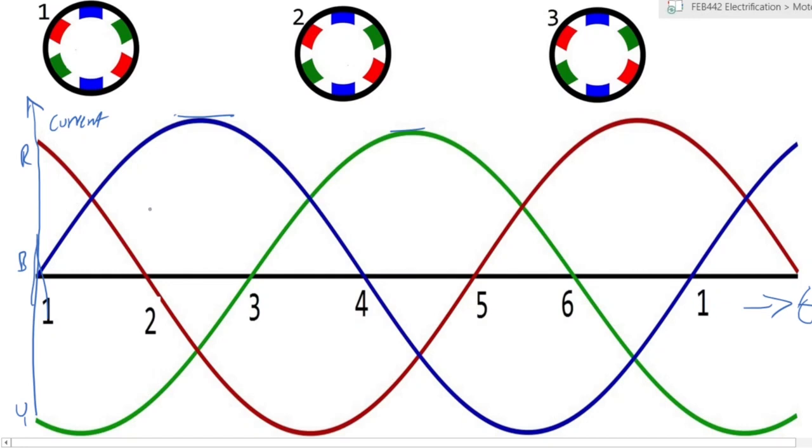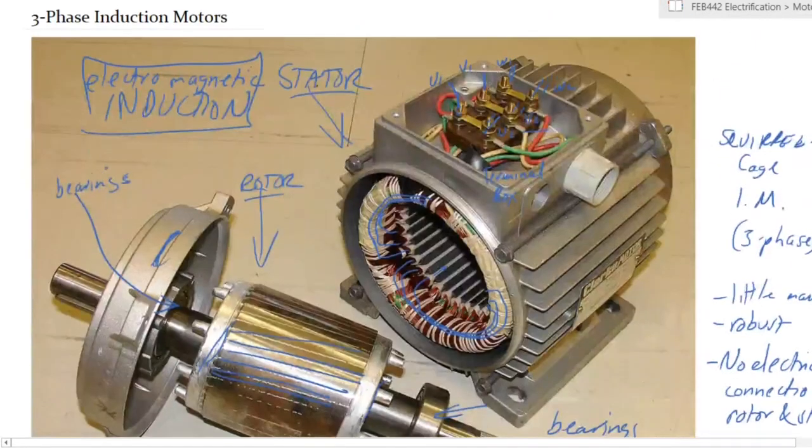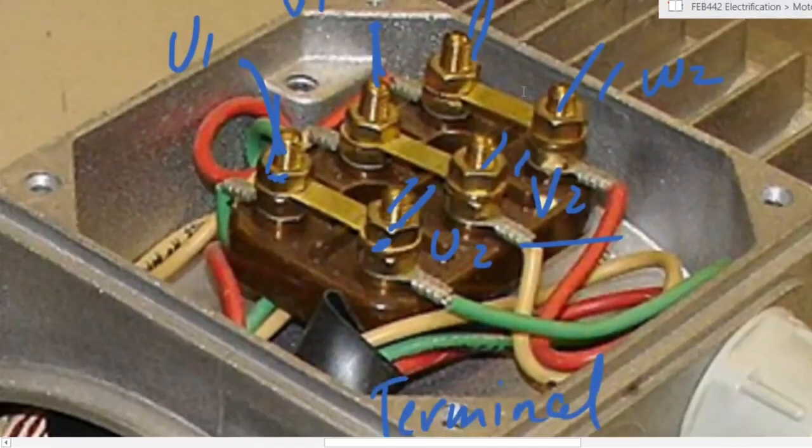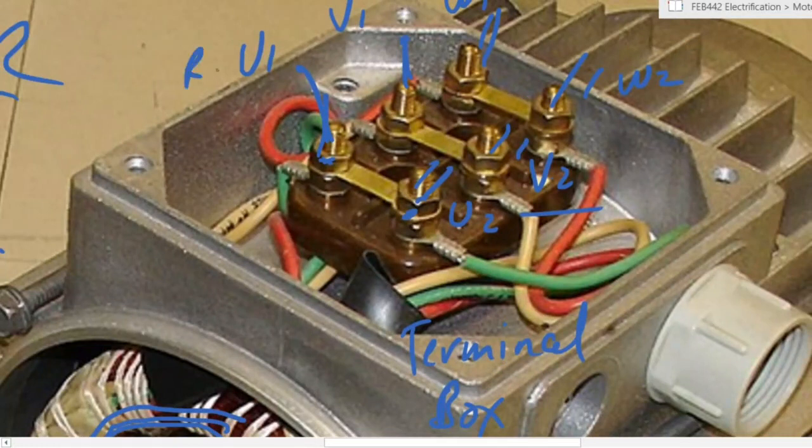Then number two, let us assume the red phase is connected to a certain winding of the motor. So like if it was here, we would assume that you're connecting your red phase, let's call it U1, U2. So the red will be here and its output will be there. So this is red 1 and red 2. Likewise, say blue would be connected here. That's blue 1 and then blue 2. And finally yellow, call that yellow 2, and that would be yellow 1.